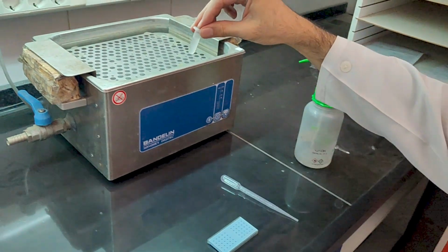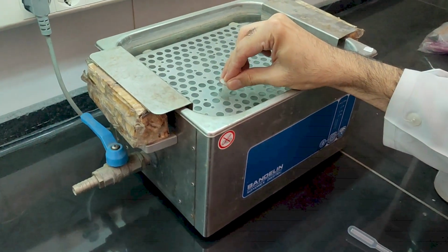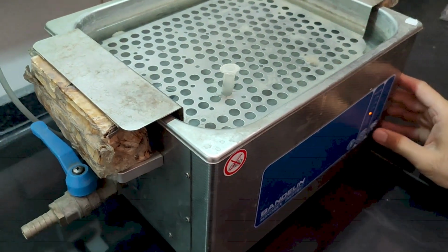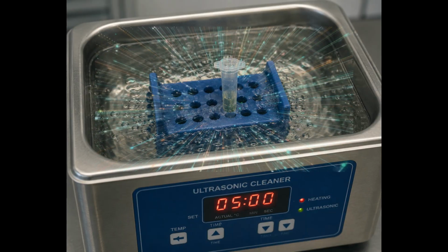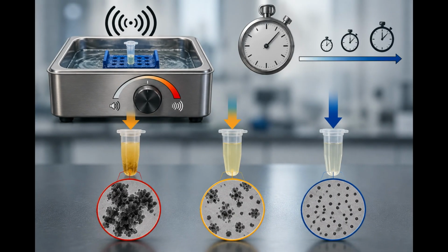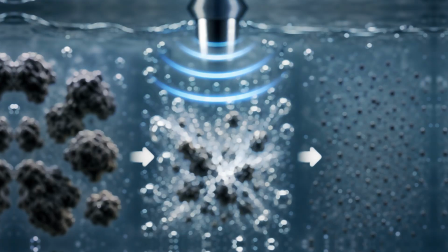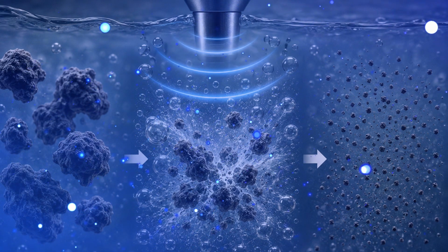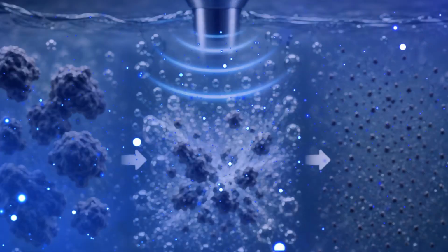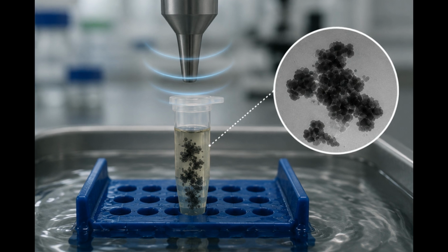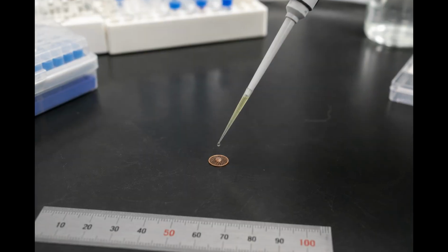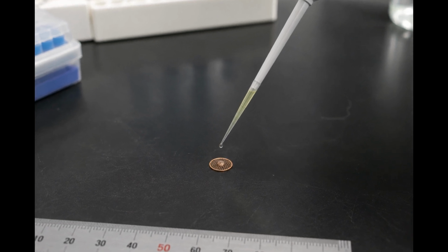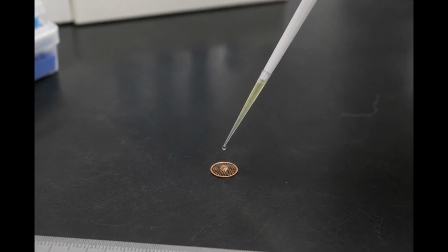I want to emphasize that the ultrasonic power and sonication duration are variables that dictate your final result. We will dive deeper into the physics of sonication in a future video, but for now, remember, excessive sonication can damage the delicate morphology of your particles or induce thermal instability. Insufficient sonication, on the other hand, leaves you with persistent clusters. Calibration is key. Once your suspension is ready, use a micropipette to carefully deposit a few droplets onto your TEM